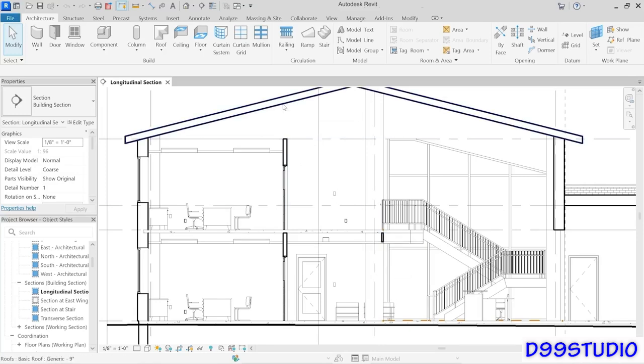There's a roof element that's being sliced through, and those are nice and bold on the edges to indicate that they're being sliced through. Ceilings, on the other hand, here, and this floor element, they are not showing that bold rendition, and I'm not satisfied with that. It's difficult to tell that those items are actually being sectioned through, and I want to address that. So that's going to be a job for object styles.